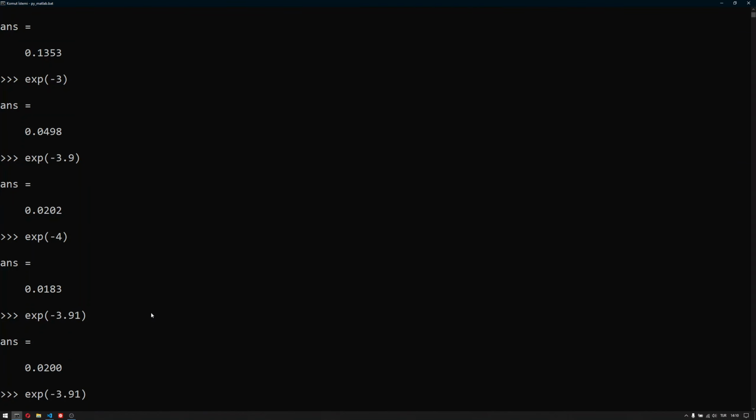Basically, if we have 1 minus 3.91, we reach the 0.98 band. And I can assure you that this will not overshoot, because this will not get bigger than 1, because at maximum you can have 1. This is an exponential term. So there will be no overshoot. This is a first order system, and I can see that in approximately 3.91 seconds this system will settle down and reach the steady state sort of behavior.